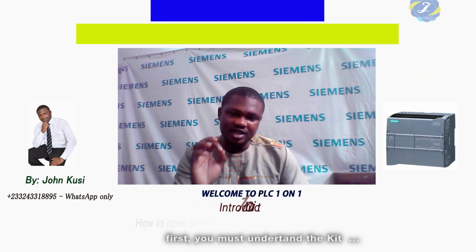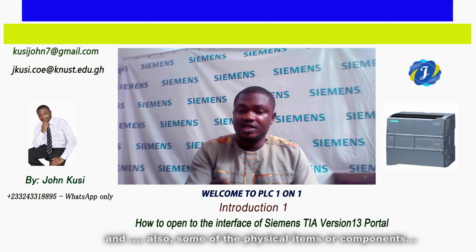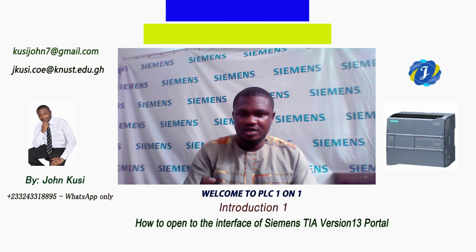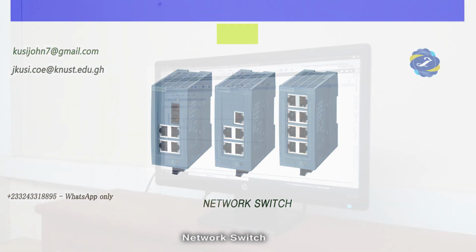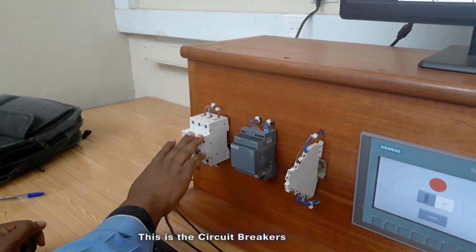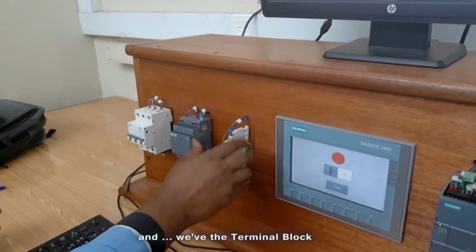First, you must understand the kits. So I'm going to take you through the various steps you should go through and also some of the physical items or components you will find when you see an automated kit, especially the one for training. We are using a PLC, circuit breaker, 24-volt converter, switches. This system needs power to work. So this is the power supply section, this is the circuit breakers. This is a 240 to 24 volts DC converter, and we have the terminal block.